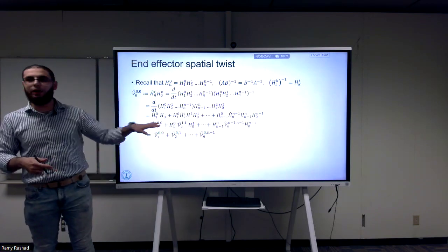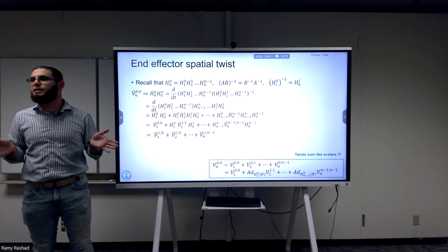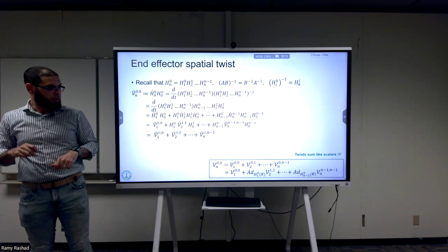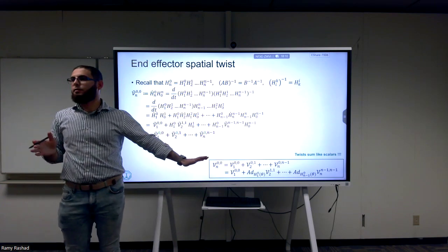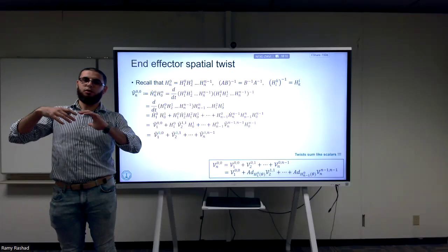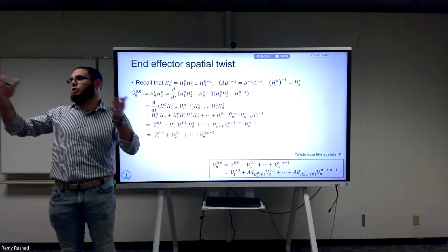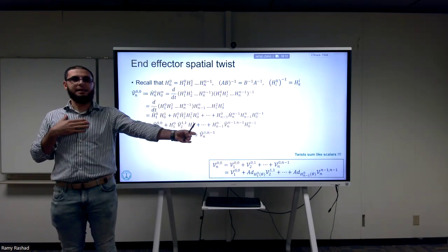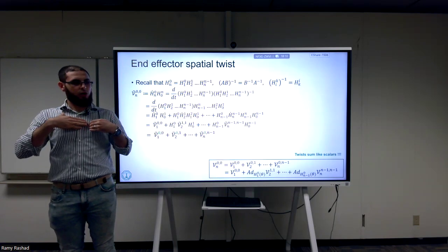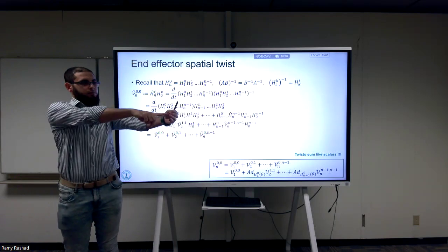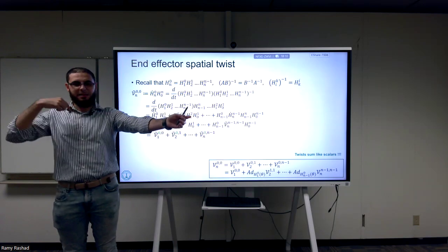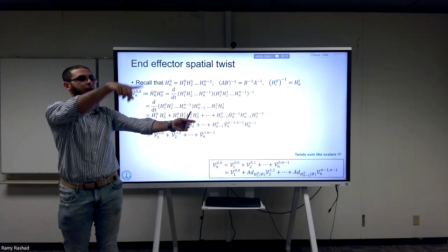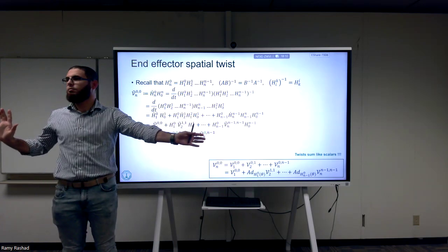If this is all in the tilde form, I can also have them very easily in the vector form, the 6-vector form. And it makes complete sense. This is what you were introduced to with velocities or positions a long time ago when we were talking about the planar case. My velocity with respect to you is the same as your velocity plus your velocity with respect to him. Makes sense, right? It's very intuitive.